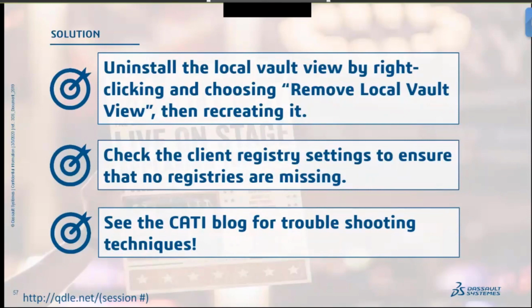We don't necessarily recommend doing this because you are going through your registry settings. But if you do reach out to CATI or Inflow support, we could typically help take a look at this as well, along with your IT department, to make sure that everything is where it's supposed to be. We do have a nice blog on our website, so if you find yourself with a little bit of time, feel free to visit the CATI website and the blog site and see some of the troubleshooting techniques that we have for things like this. But typically what you want to do is keep it out of the box, remove that local vault view, and then recreate it, and that should fix the error that you're running into.